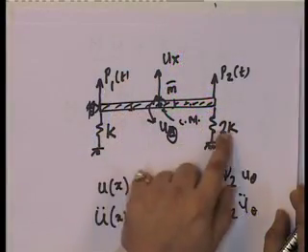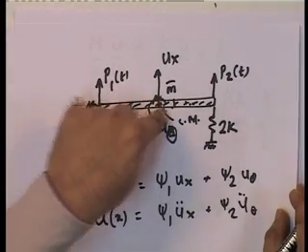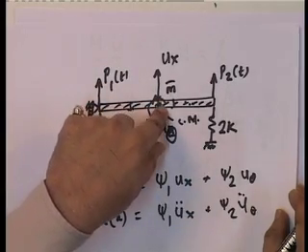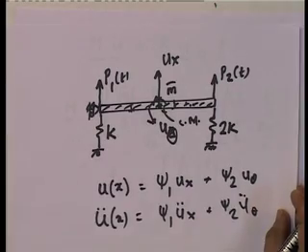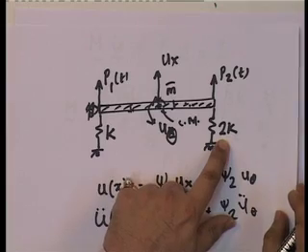What is the center of stiffness? The center of stiffness is where, when you apply a static displacement, the net force goes through. When we had uniform stiffness over the entire thing, the center of stiffness was at the center of mass, and if the center of mass and the center of stiffness are at the geometric center where I have defined my degrees of freedom, I have uncoupled.